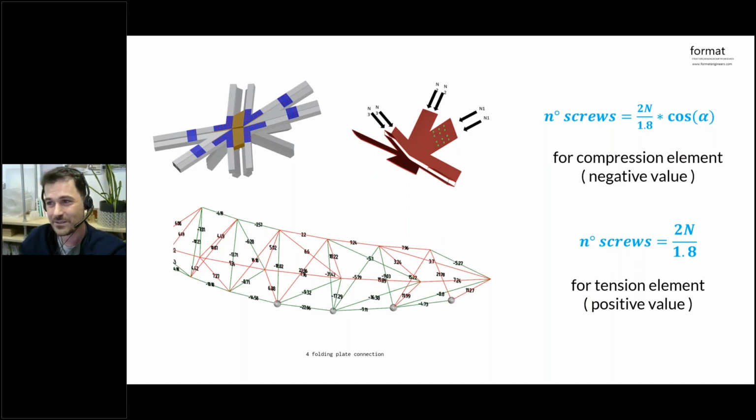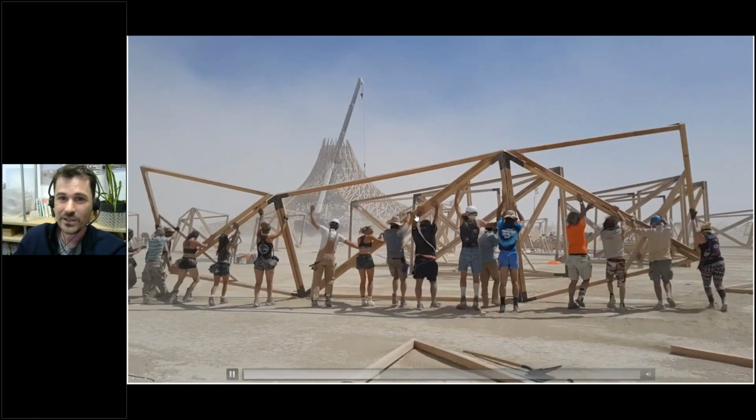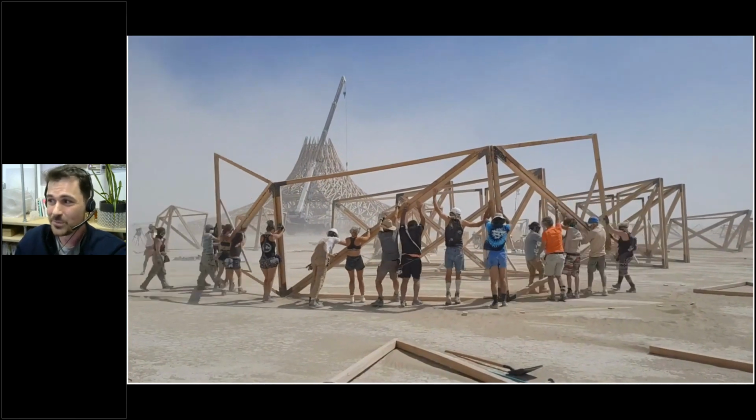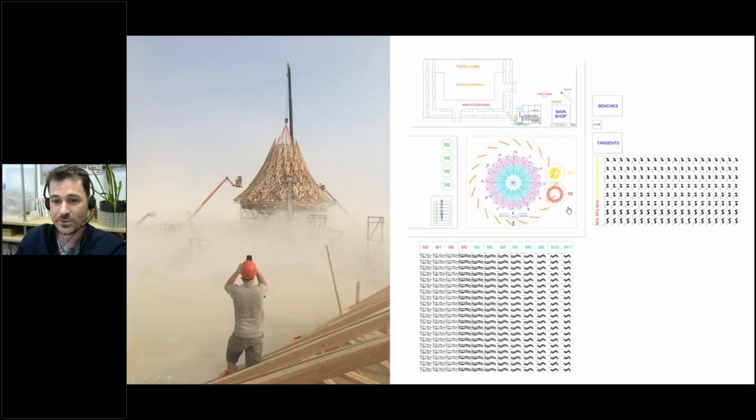Engineers were sending us the formulas and the forces from Karamba, and we received the compressive and tensile values, and they gave us an equation for each screw. Every one of these brackets was thought of in relation to the forces going through the structure. So we could tell people, if you see one that is longer than others, it means more kilonewtons are going through it. And this was really interesting: this honesty about the construction process, about the funding, about the cost, about everything had to be a constant discussion.